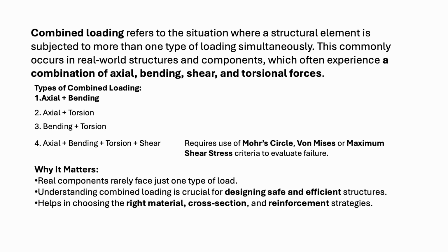So in this case, when we are talking about combined loading, we are talking about axial plus bending, or axial plus torsion, bending plus torsion, or all of them together, axial plus bending plus torsion plus shear, when we require the use of Mohr circle, von Mises circle, or maximum shear stress criteria to evaluate failure.